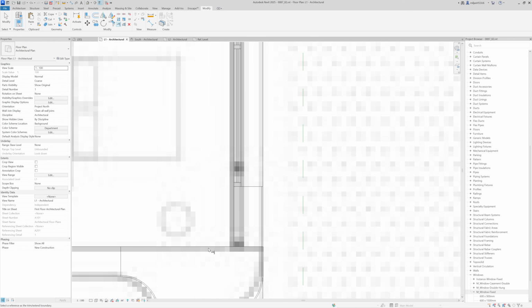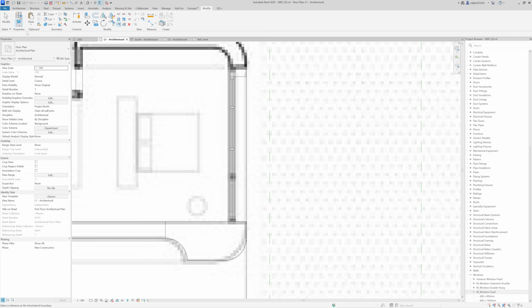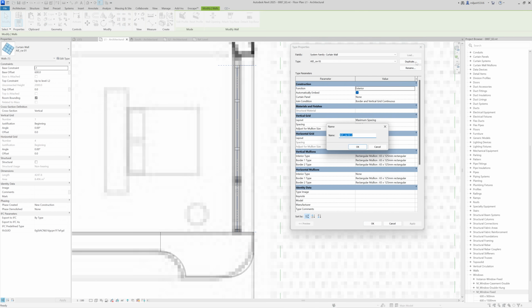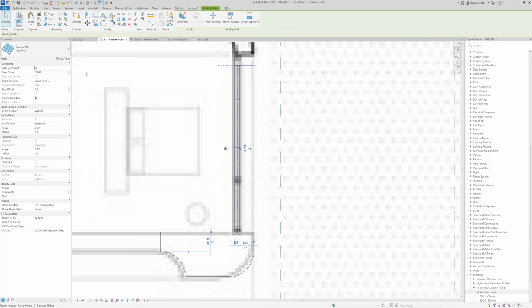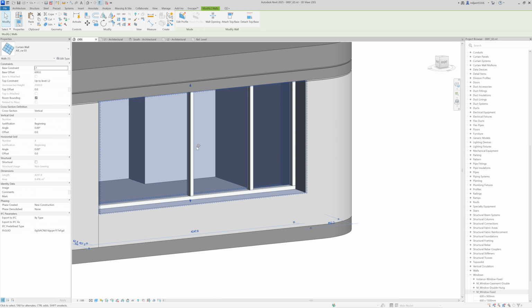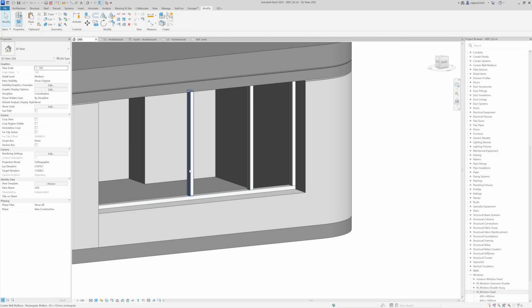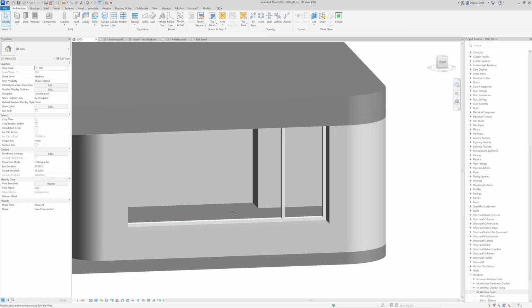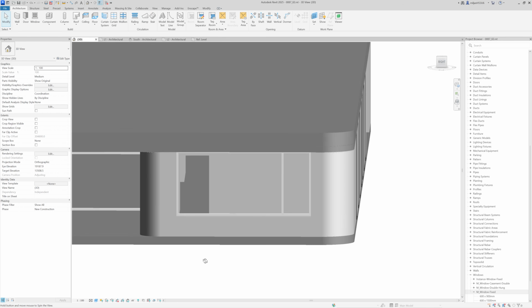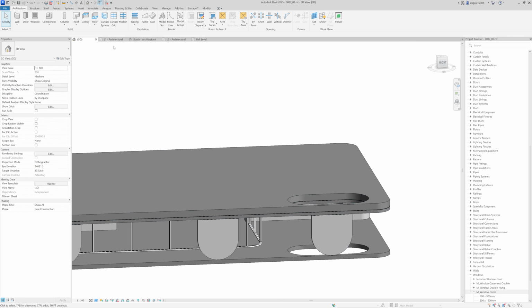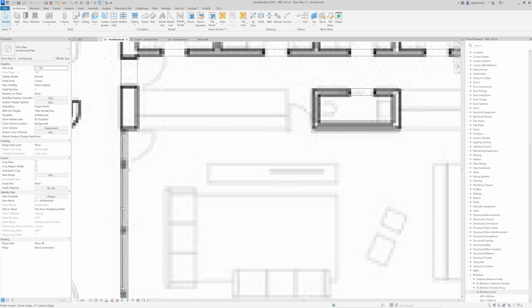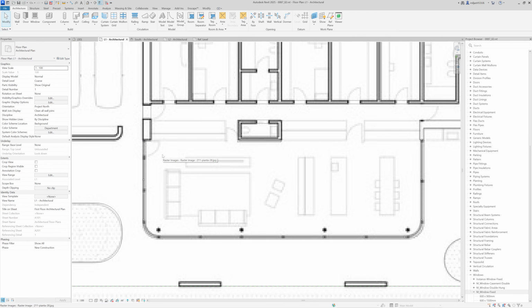But before that, okay, this one needs to go to here. So I can just, because I made something, I can just duplicate this wall type. And let's fix this. I will unpin this, and I can just delete this curtain grid, and okay, we can keep it like this. So this is okay. And let's see, what do we have next? So we have to place doors everywhere, and then we also have to place door here for the curtain wall.